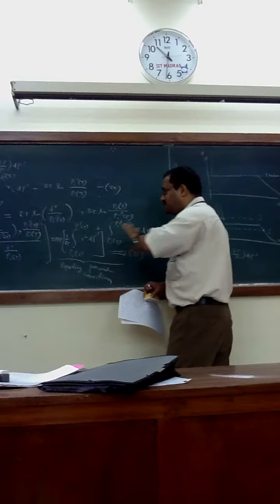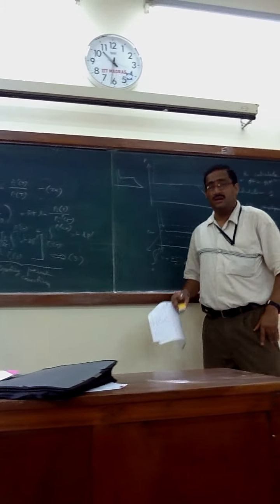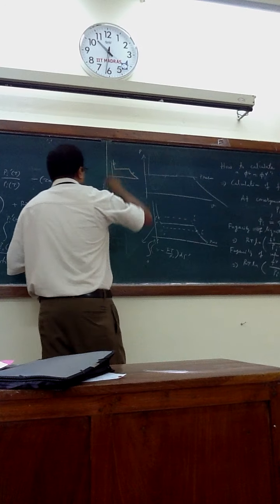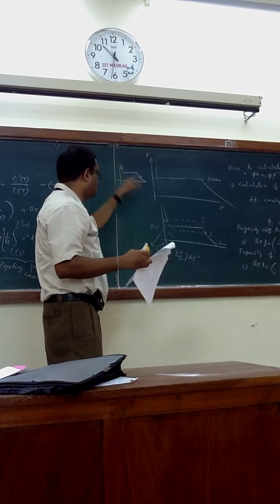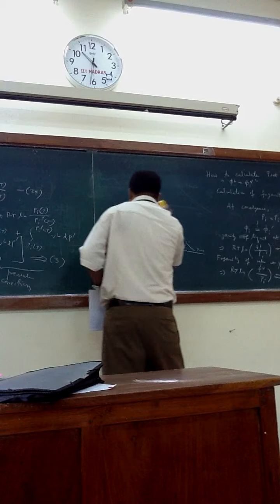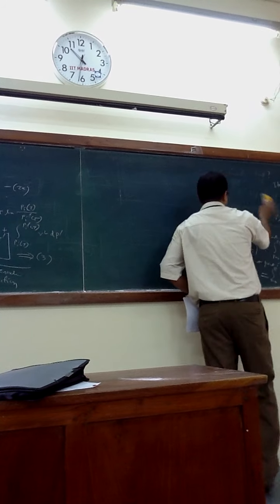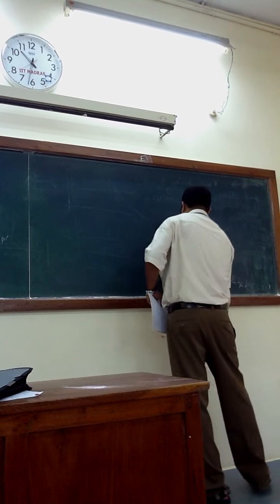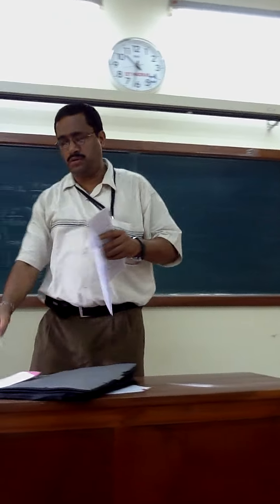This Poynting pressure correction is important if you calculate the fugacity when it is not in equilibrium. If you want to calculate the fugacity and you know the vapor, in that case you can do the Poynting pressure correction. I will come later to those calculations. But here, if the Poynting pressure correction factor is 1, that means the integral is 0, and in that case you are at equilibrium. So what will be the iterative procedure?